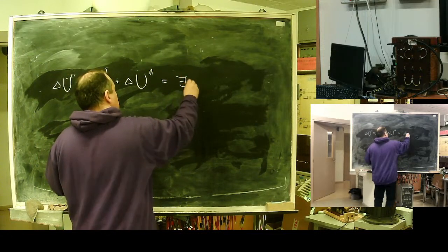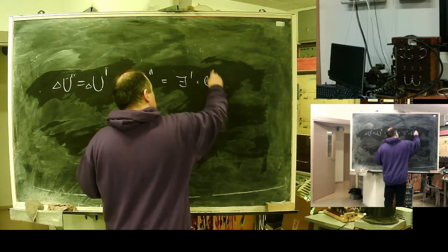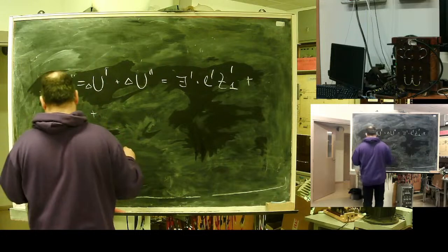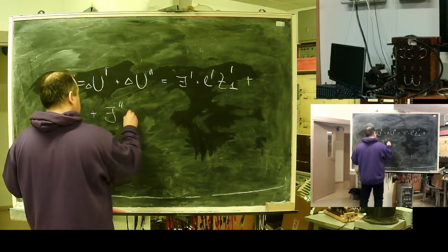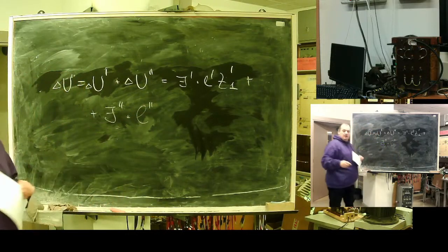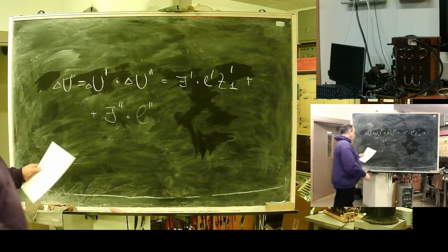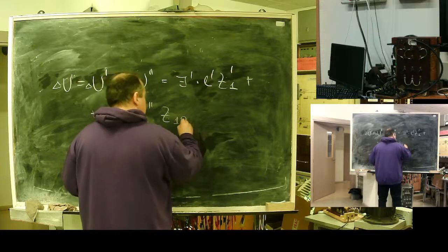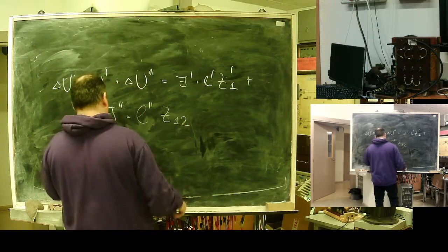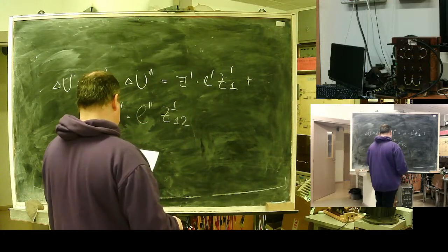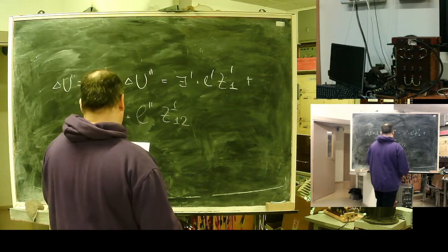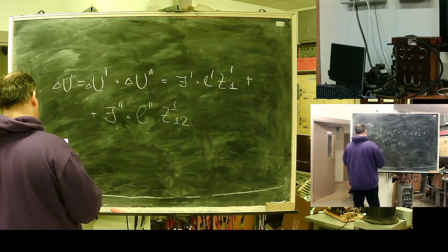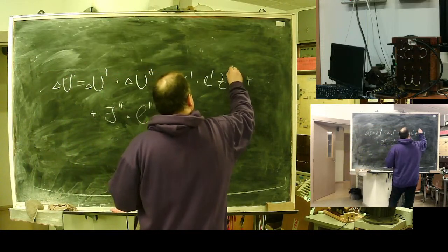This can be written as I1, first line length L1, direct sequence self-resistance of the first line, plus my current in the second line I2 multiplied by L2, the length of the common part, multiplied by, it can be represented as, a mutual Z12.